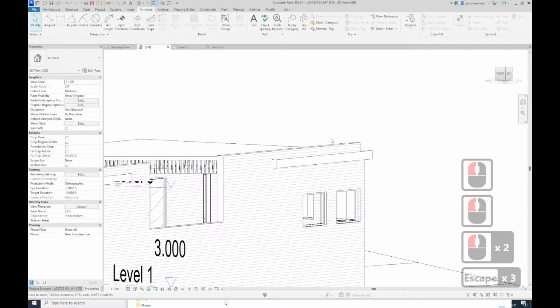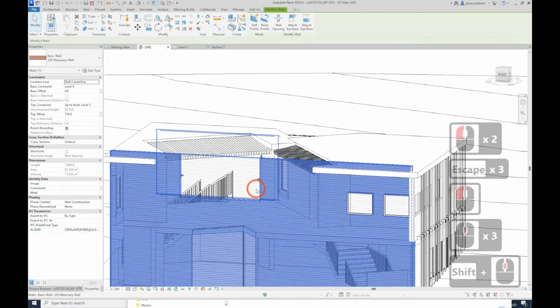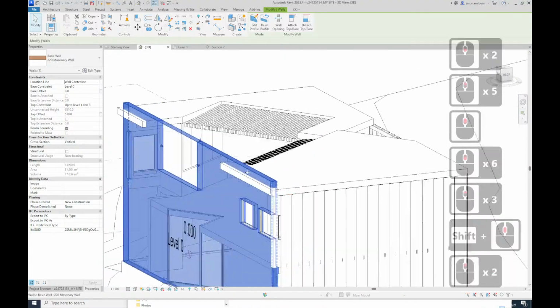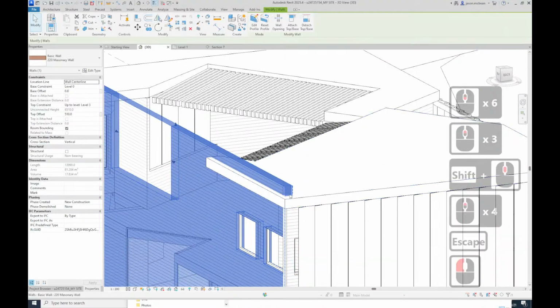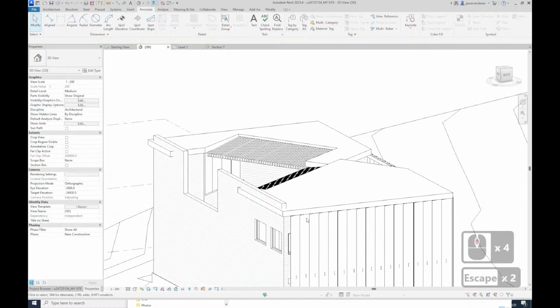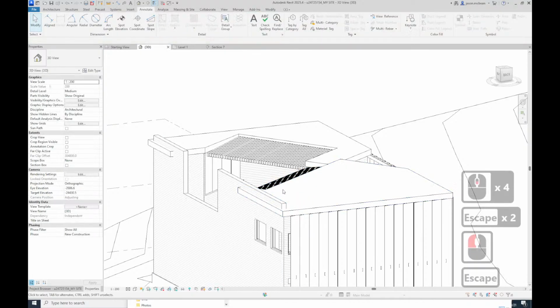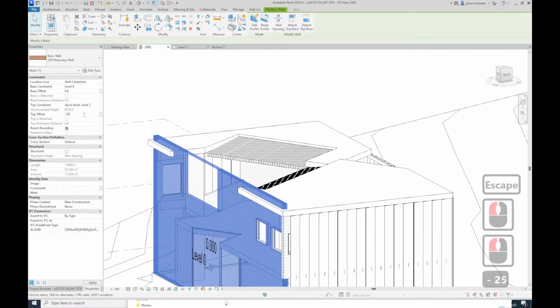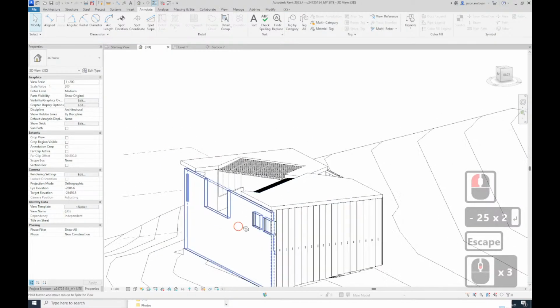Do you need a parapet? Yeah, depends. You need to decide. It interferes with the design if it has a parapet. You can emulate a parapet like I did with my model, where I put coping, so it looks like a thin roof, but there's a parapet behind. So you need to decide. But this technically will stop minus 255. It will stop beneath the roof slab.